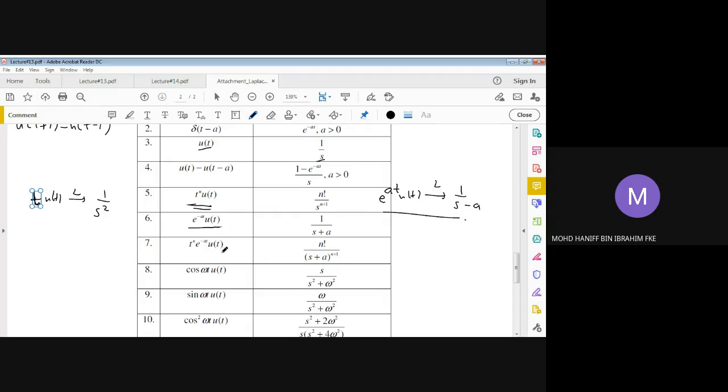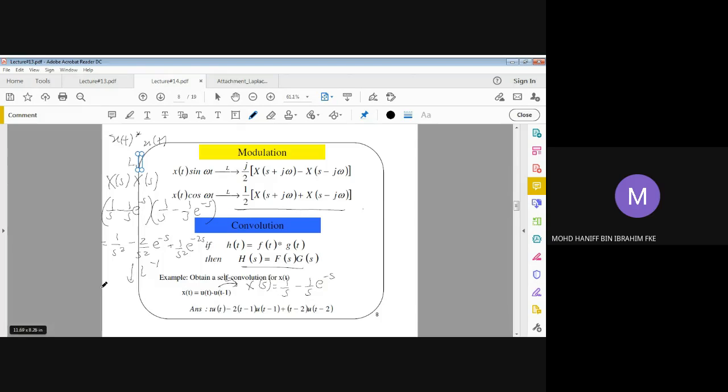So that's why I'm referring to signal number 5: if we have t u(t) functions, the Laplace for it will simply equal 1 over s squared. So we're going back to lecture 14, in which if we have 1 over s squared as the s domain signal, the inverse of it shall equal t u(t). Okay, so you got the point there? That's why for the inverse of this, we're going to have t u(t) for the first term.